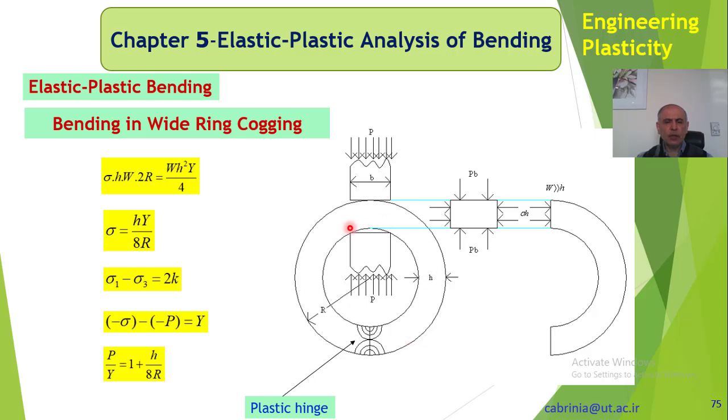Don't forget that here we have assumed complete plastic deformation, and we have assumed that it's a rigid plastic, so that no strain hardening is taken into account. So the P that we obtain is for incipient yielding or a start of the deformation, and we are assuming that as the deformation occurs, there is no change in load because there is no strain hardening. So the material does not become harder.